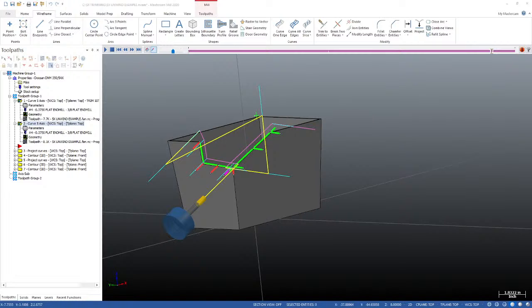The smallest tool I used was 0.02 millimeters in diameter, and it had a 0.02 millimeter corner rad for doing some mold work. That basically I was taking a 1/4 inch pin, 6 millimeter pin, and I was machining an entire mold on the tip of that pin, which was pretty mind blowing.